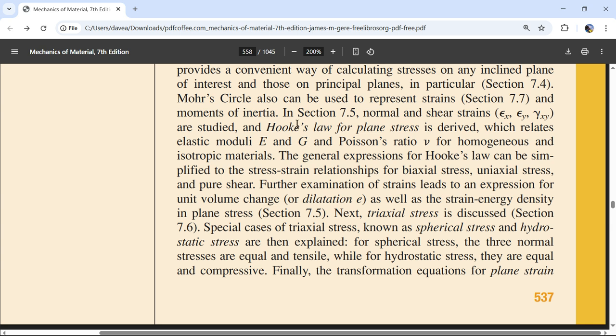Something seems a little bit fishy, but we have a shear stress is equal to the shear modulus times the amount that the angle can change. And I think I'm right on this. I think the angle can change by 0.004. A lot of times, I just do fewer shear problems and fewer change-in-angle problems due to shear, just because they're probably harder. They're just mentally harder, you know what I mean? I think shear is mentally harder to visualize.